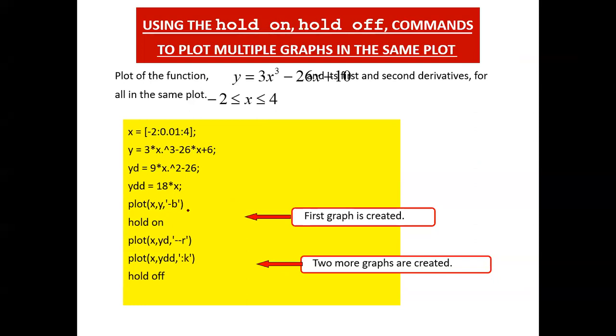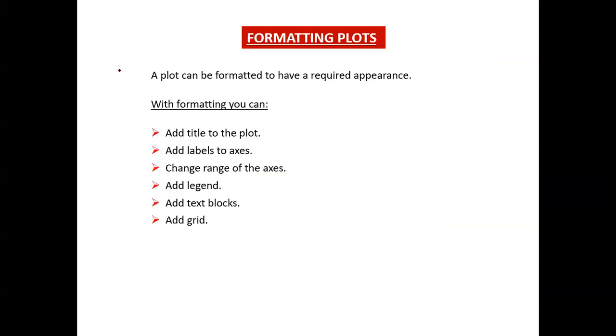So we generated multiple graphs in the same plot, and this is when we need hold on and hold off. For the two-dimensional plot, we have various formatting we can utilize. The formatting we can utilize includes adding the title and adding the label.